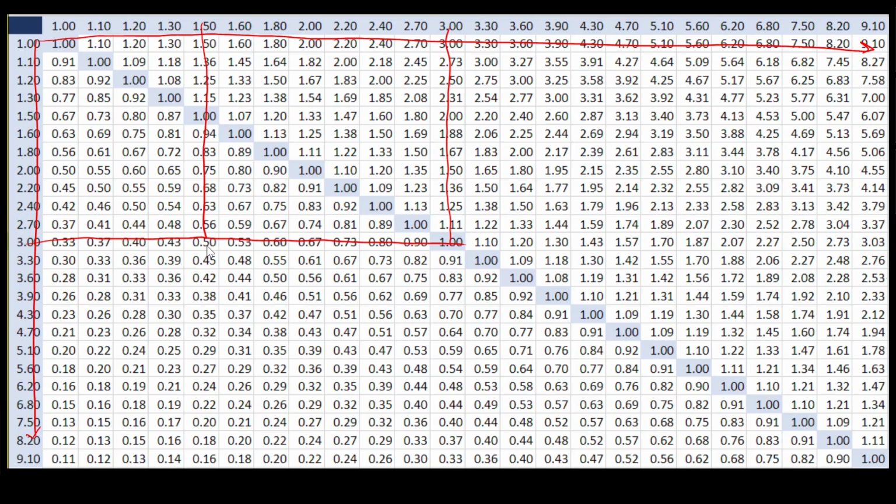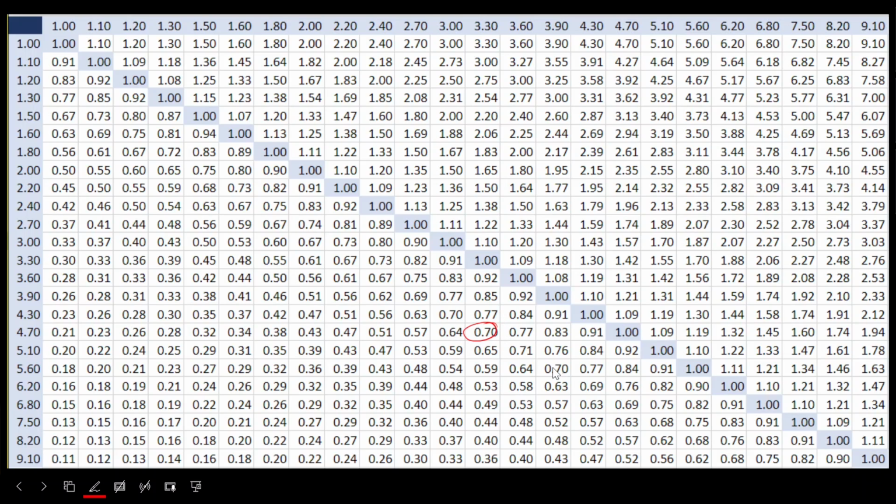In order to use this table, all we need to do is know what the ratio of resistors is for a particular gain, and then we can select the best pair. In our earlier example, the inverting amplifier required a ratio of 7. And if we look at this chart, we can find 7 here and here. By the way, disregard any factors of 10 because we can easily find the desired resistors, because there are, in this case, 24 values per decade.